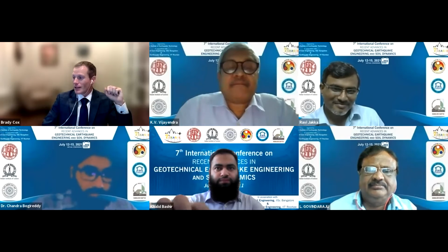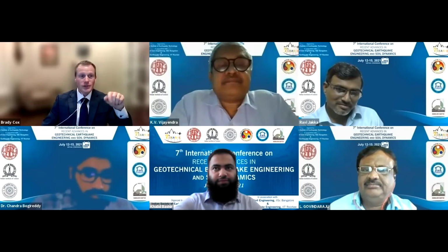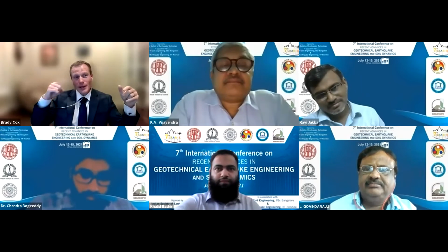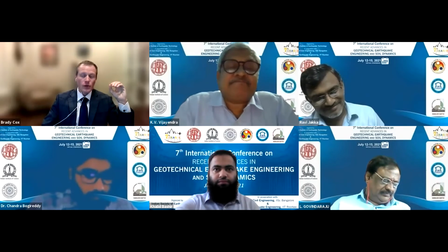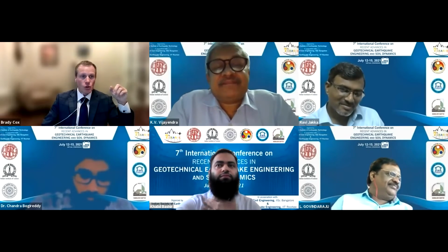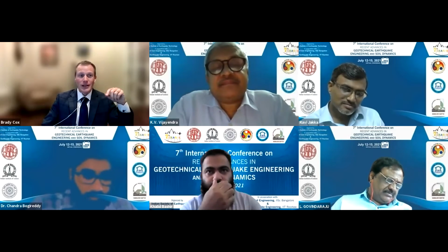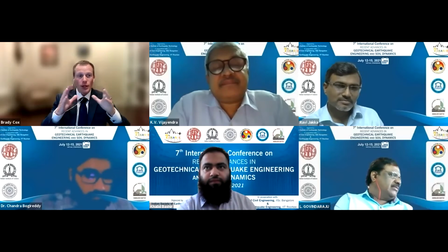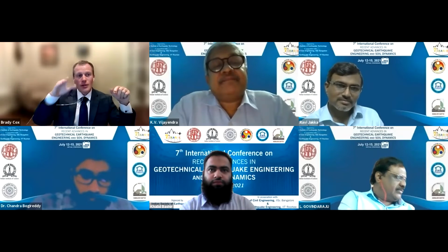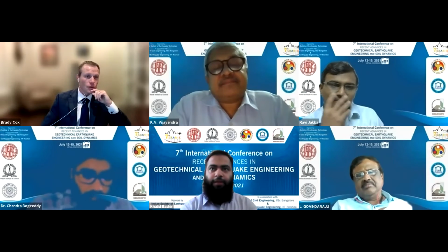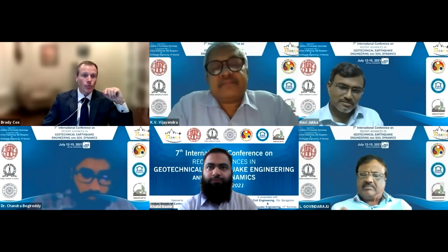So we've studied that, and indeed, sometimes as we increase the area, we got slightly worse results until we increased the area to a certain point, and then the results got better again. We have to be careful about reading too much into the R value because it's only one metric of showing the goodness of fit. What we found, and I didn't show this, is that the misfit continuously decreased as we incorporated more and more area. So while the R value fluctuated up and down a little bit, the transfer function misfit actually continuously decreased. We talk about that in our paper, and I gave the references to the paper. They're at the end of the presentation.